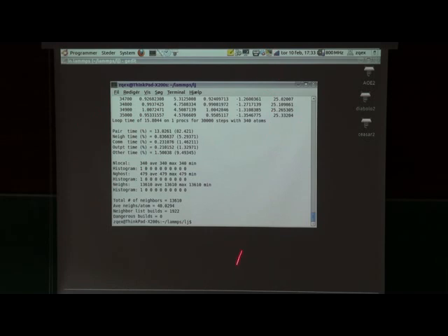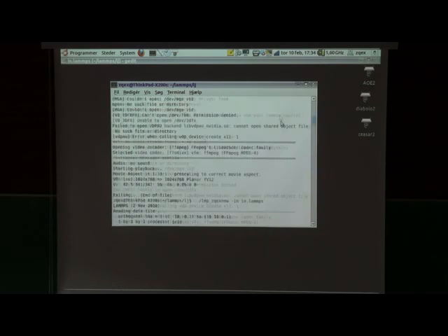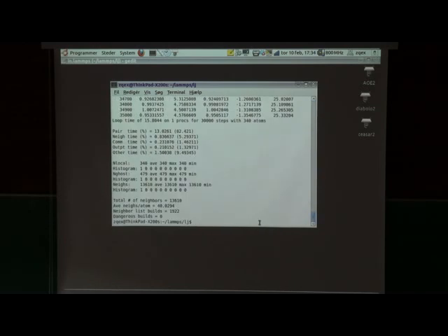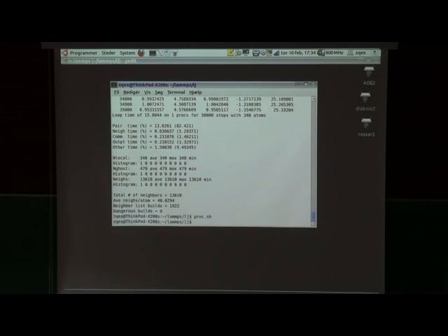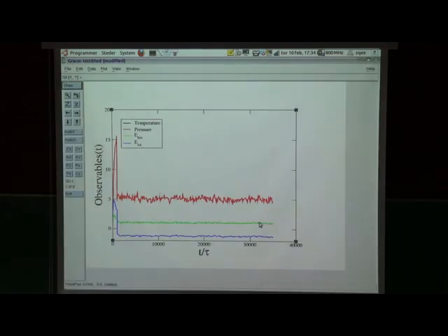I just ran the simulation, and what you can see here is the dangerous builds field equal to 0, which means that my Verlet lists were rebuilt often enough as not to have dangerous configurations. And there's a lot of thermodynamic information that has been dumped. So I've prepared a small script that processes all of this, and now I can just plot the thermodynamic information.